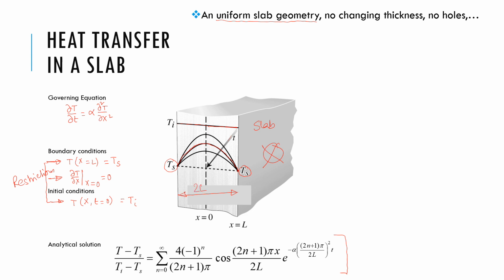What's another restriction? The boundary temperature. It's nice to write this, but it means the boundary temperature cannot change with time. If it changes with time, this is not the solution. In fact, in general, we cannot solve such a problem.